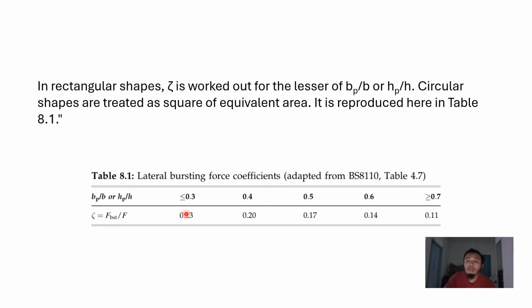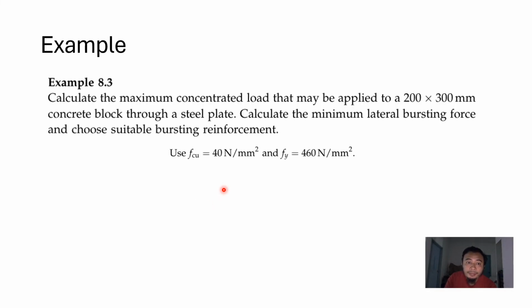So basically you're transforming more of your axial force towards the bursting force. It depends on your members, depends on the components you are using. But there are solutions for everything. So if your bursting coefficient is high, then you need to design for a higher steel area. So let's take a look at the example here.